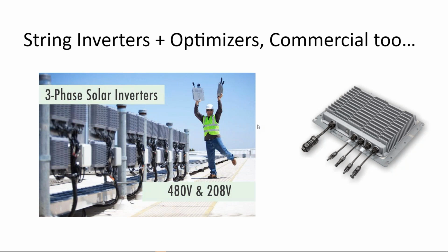So in a dumb system where you're just backfeeding onto the grid and there's a grid failure, it needs to de-energize. That doesn't mean you can't be supplying a critical load, but the fire department still needs some means to de-energize the system if there is an actual emergency with the solar array at the building level.